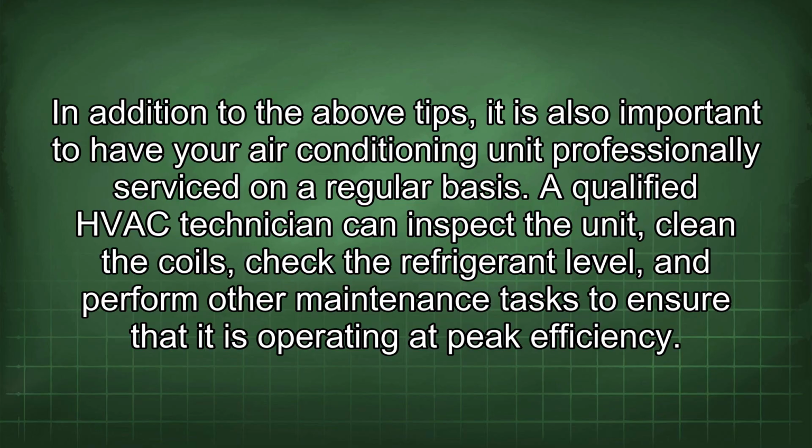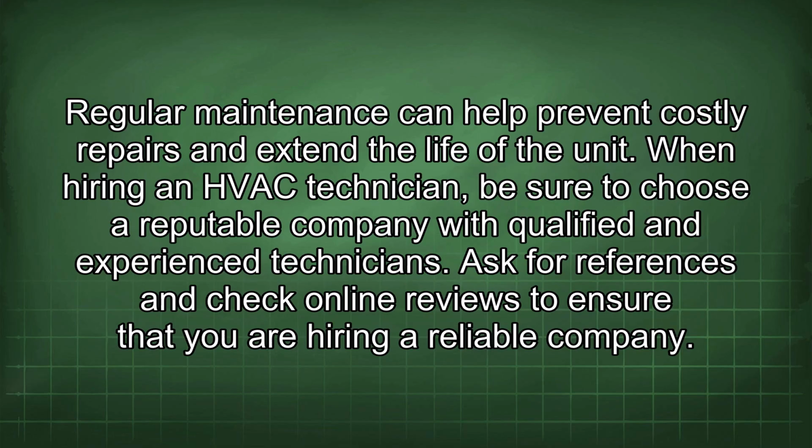In addition to the above tips, it is also important to have your air conditioning unit professionally serviced on a regular basis. A qualified HVAC technician can inspect the unit, clean the coils, check the refrigerant level, and perform other maintenance tasks to ensure that it is operating at peak efficiency. Regular maintenance can help prevent costly repairs and extend the life of the unit.